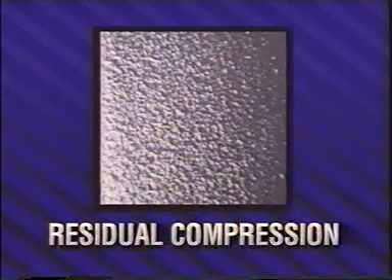Since most cracks originate at the surface of a part, it stands to reason that placing the surface under compressive stress could be beneficial. And this is true. To increase the fatigue strength without increasing the weight of a part, many surface treatments are used to add compressive stresses: nitriding, carburizing, shot peening, surface rolling, and overstressing, just to name a few. Work hardening and processing operations are used to increase residual stresses. Applied properly, these treatments put the surface in a state of residual compression.